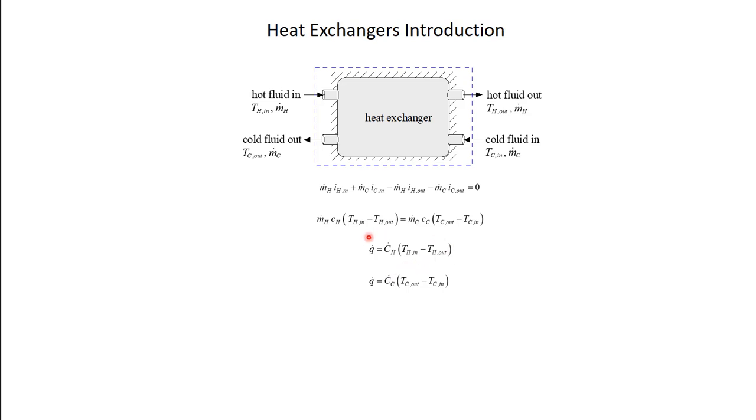If I have a fluid that is evaporating, a pure fluid that's evaporating at a constant pressure, that's a case where I can put energy into that fluid and its temperature won't change at all, right? That's a capacitance rate of infinity, right? So that's getting to the highest capacitance rate you can have.